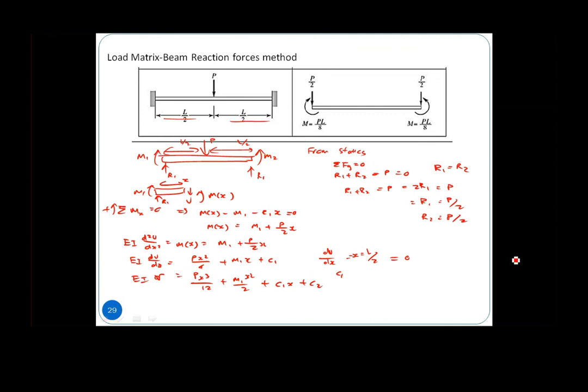So we can find two boundary conditions to help solve it. We have v equal to 0 when x equals 0, then we know that our C2 equals 0, so this part is 0. Also dv/dx at here is equal to 0 when x equals 0, so we also have C1 equal to 0. So this part is also 0.